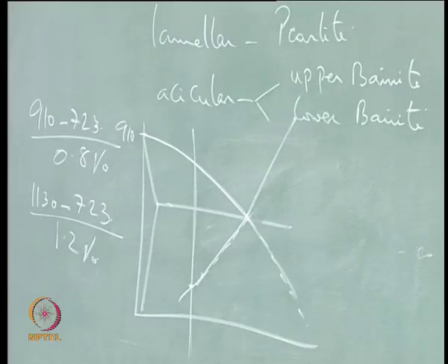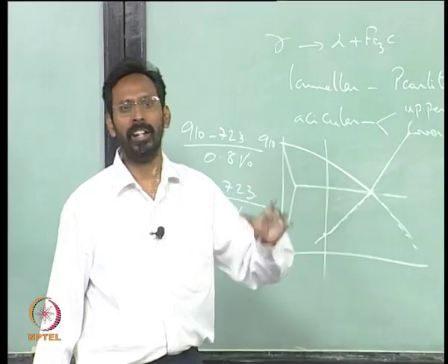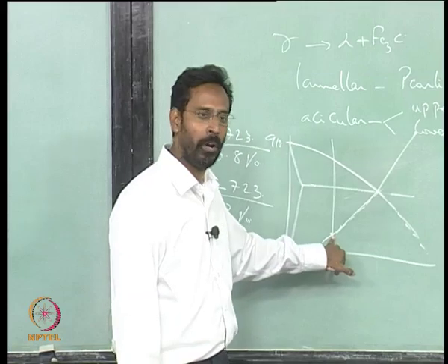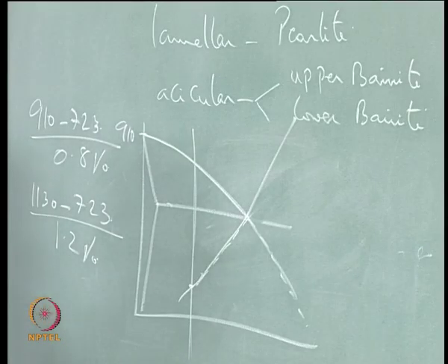So you can get things like that, and if the temperature is too low, you would get bainite instead of pearlite. You would get one of the two phase mixtures, either pearlite or bainite, if you are below that, provided nothing has happened before it. Okay, we will stop here.